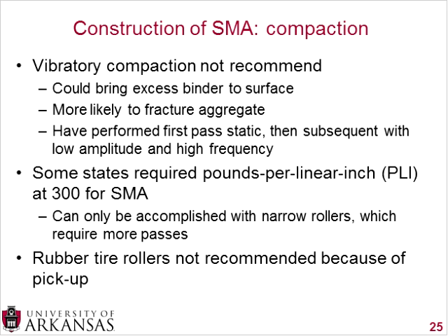Now, they do sometimes put a vibratory compactor on a little later in the compaction process, but they definitely recommend leading with a static roller. And then if you feel you need that vibratory compaction, you can do subsequent compaction on a low amplitude, high frequency basis.